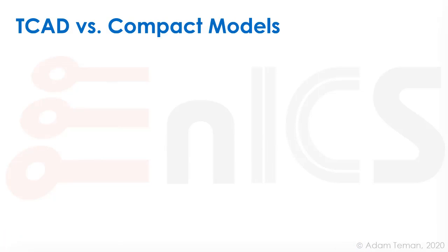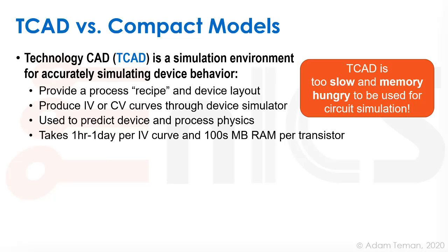Before we start discussing basic MOS models, I want to discuss the difference between TCAD and compact models. TCAD, or Technology CAD, is a simulation environment for accurately simulating device behavior. Basically, it's a very, very accurate simulator where we provide a process recipe and the device layout. Doing this, we can produce the IV curves or the CV curves, IV being current versus voltage, CV being capacitance versus voltage.